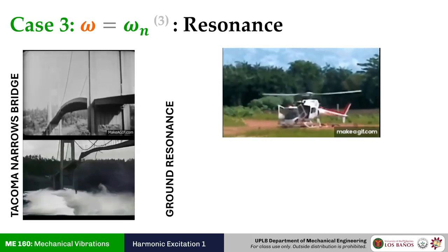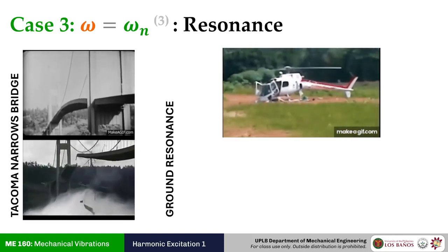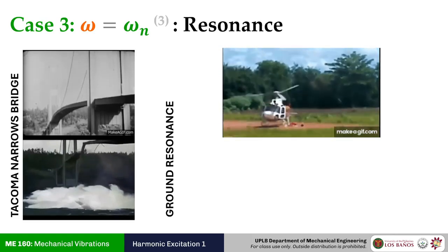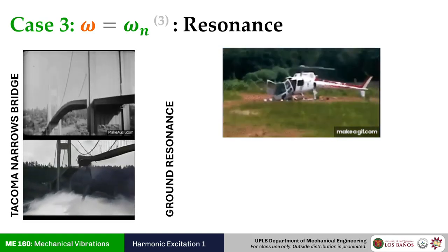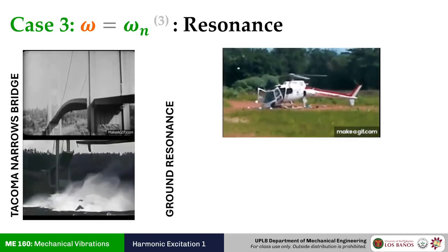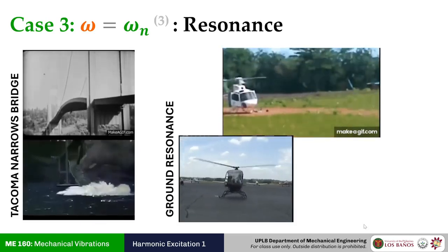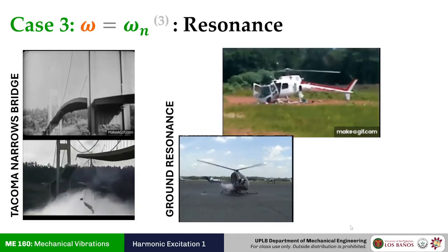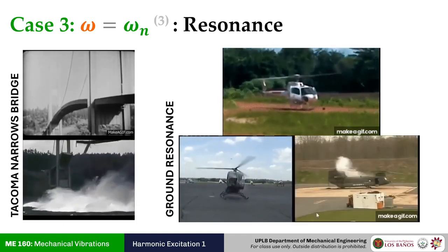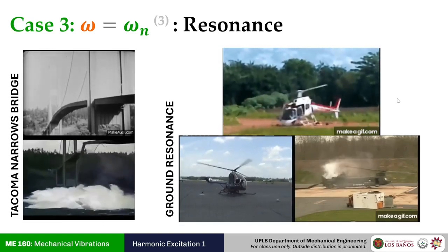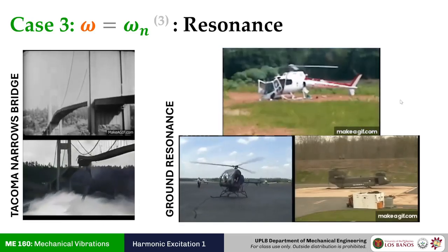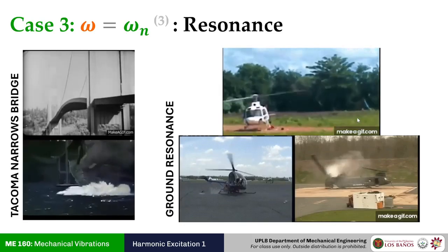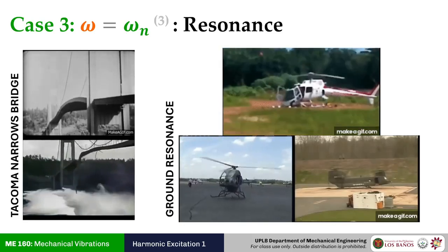Another resonance phenomenon is ground resonance. It occurs when a helicopter hits the right tempo. When I say hit the right tempo, its landing gear hits the ground at a particular timing, and it causes the pressure waves from that contact to reverberate with the natural frequency of the helicopter. So it's just gonna go kaput, essentially. So if you see here, the resonance takes its time. It's not going to be instant, but it will destroy your system because the vibration gets worse and worse. So that's resonance for you.